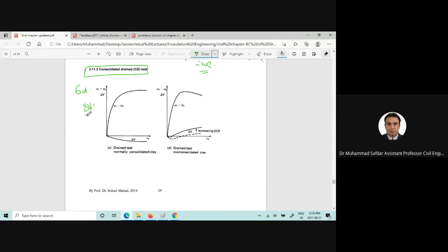and delta, the volume will change. So we can draw the stress strain behavior, something like this, and the volumetric behavior, because it is negative, which means it's compressive for the normally consolidated clays and for loose sands. For the case of over consolidated clays or dense sands, we can see the stress strain behavior at very small strains compared to the other one.